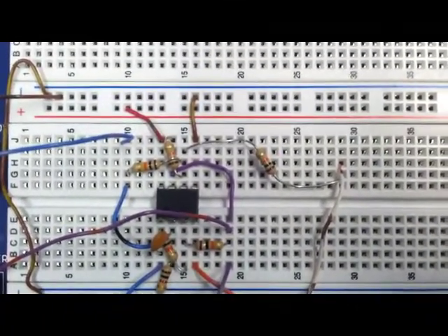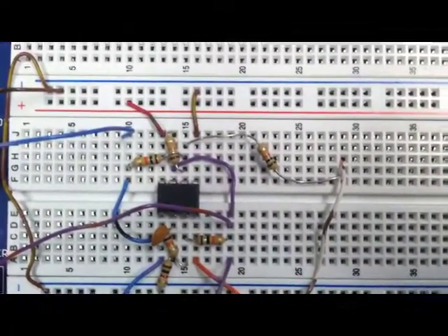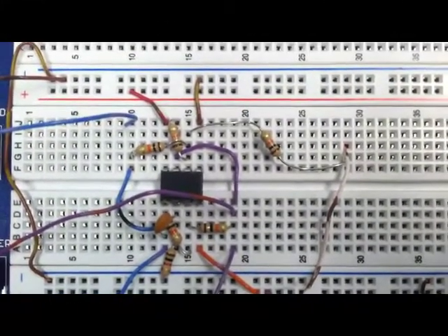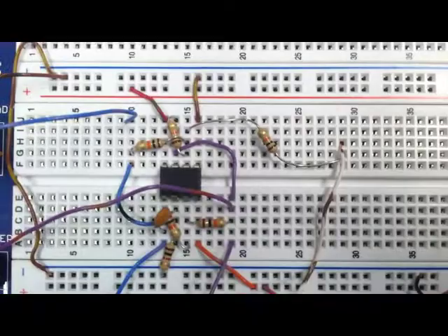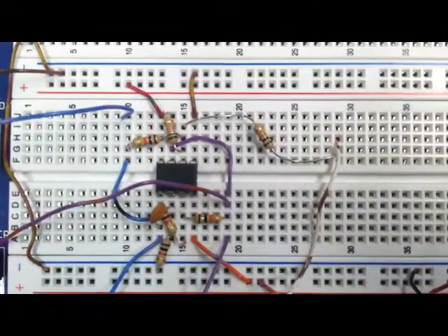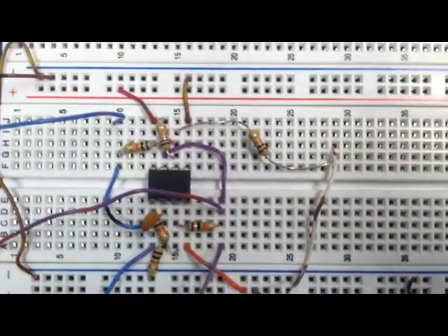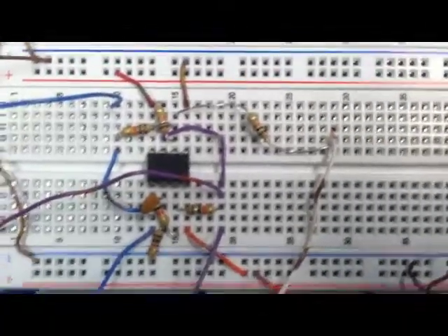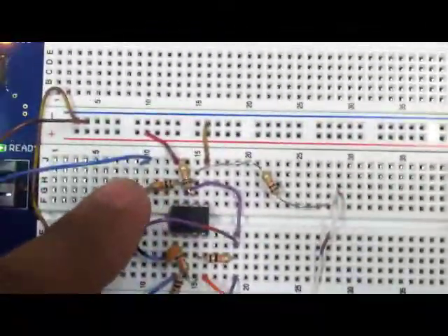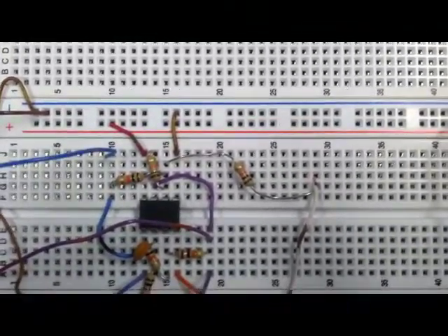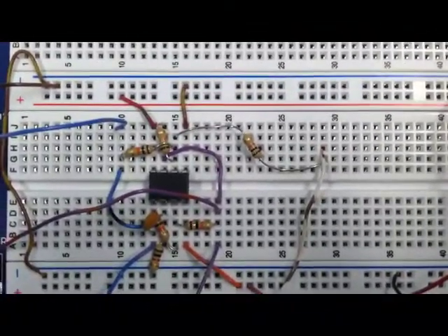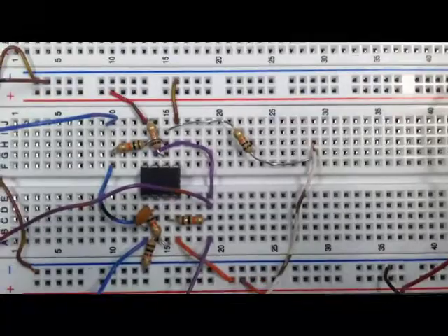I've powered the circuit with external plus or minus 5 volt supplies, a function generator that is giving an 8 volt amplitude sine wave at a frequency of 100 Hertz, and the output from the Schmidt trigger, which is V out right here, and V in, which is right there, is going into the analog inputs on the myDAQ. So let's look at those connections.